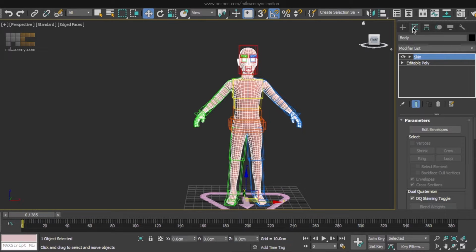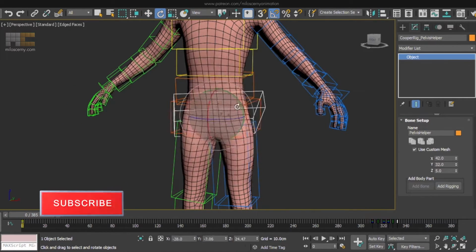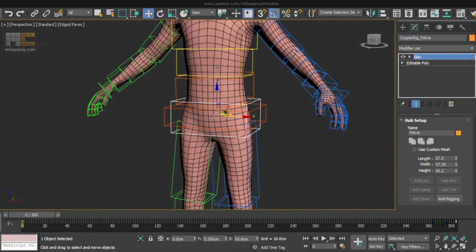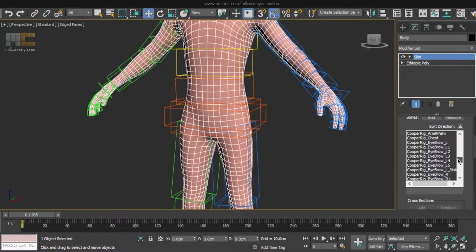However, there is one mistake I did before. Before we edit all the bones to the skin modifier except the platforms and the main cat triangle, which is still correct. But that means we currently have both pelvis helper and pelvis bone in skin modifier. But that we don't want. The main pelvis bone shouldn't have any vertices weighted on it, because all of those will be on pelvis helper, so we can remove pelvis from this list.